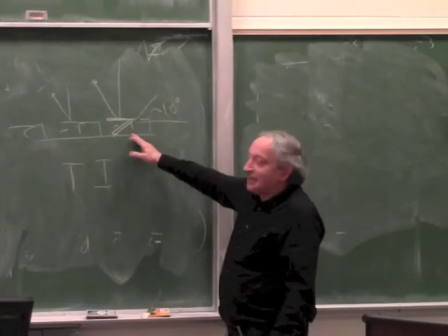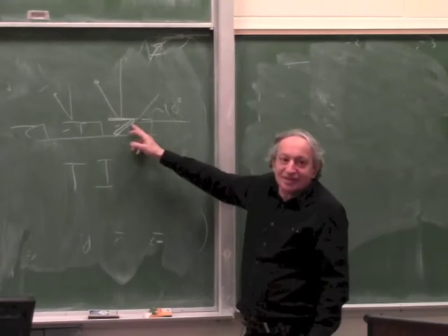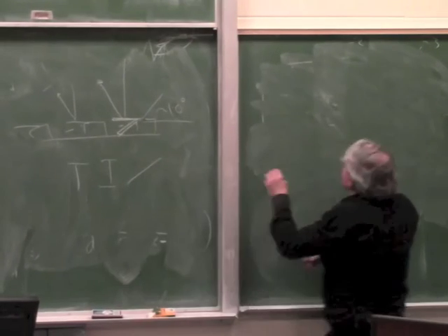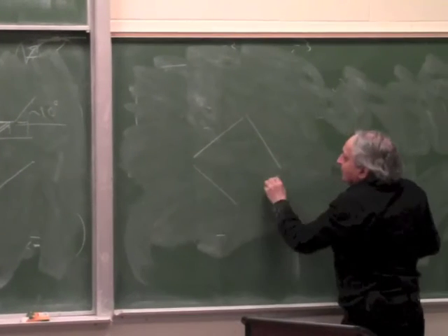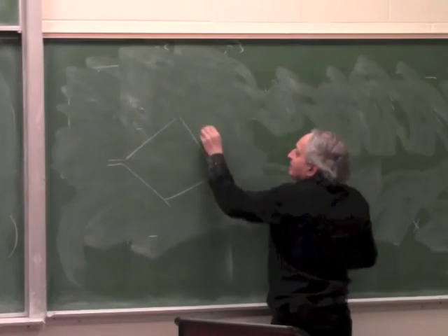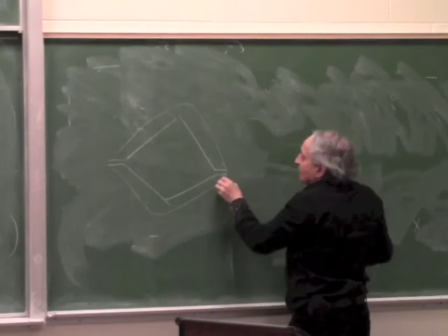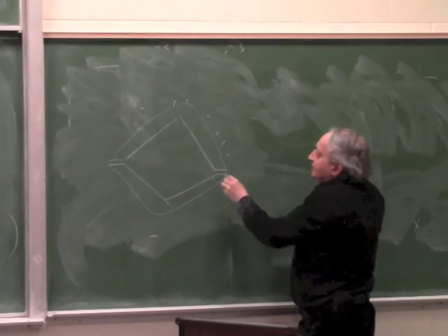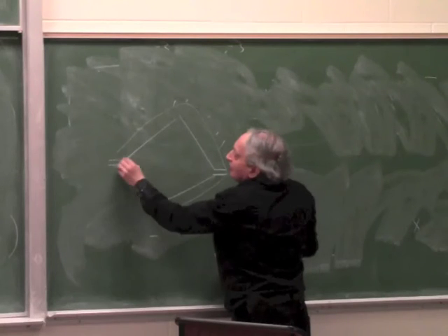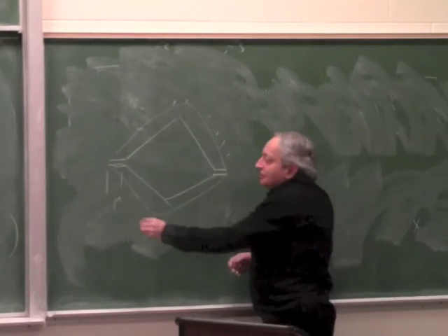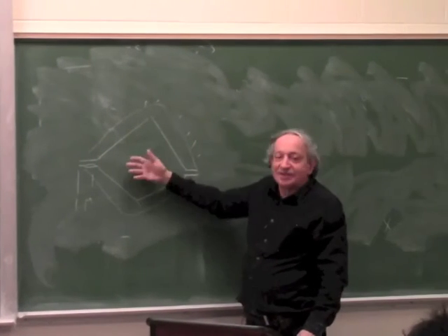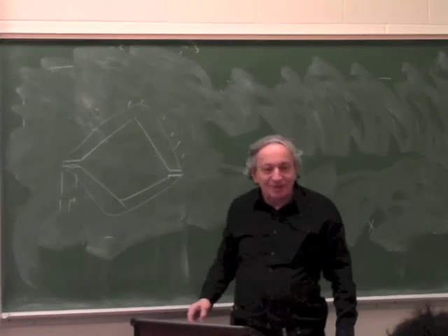And if you really want to see how they make them, they look like this actually. They are not a cantilever, because this will fatigue too fast. So actually each mirror looks like this. And then here they have a strip, and it's a torsion hinge. So this is the opening. This is steady, and this mirror tilts like this. The torsion hinges are about 1 micron long by half a micron wide, but they only twist 10 degrees and they last forever, which is quite surprising.